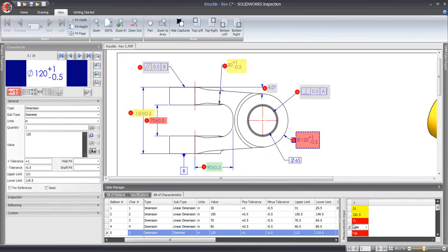But all this is okay where the components are simple. What if you have a component which is very complex? In that case, normally we use a CMM machine to do it. All these things I've showed can be measured using the digital caliper. Your digital caliper can be connected to a USB. Nowadays there are calipers which can be connected to a USB, and you can connect it to your computer, and while you are measuring, you can see all this will be captured here. Whatever value we have here, it will tell you whether it's correct or incorrect. Okay, so that is how it can be done.